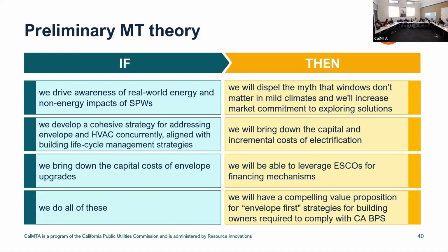And at that point, this needs to be part of our investigation and our research in the next phase, and encouraged by some of what we're seeing with things like the case study from ASHRAE, where they did the energy walk and looked at what would happen. They did the energy walk with, let's just go with HVAC first, and what does this project look like, and then what do we do if we upgrade the building envelope to ASHRAE 2016, and then do HVAC, and learn through that process that it significantly simplified, didn't necessarily significantly change the size of the HVAC, but simplified the implementation of the upgraded HVAC system. And so I think there are mechanisms we don't fully understand, but some opportunities there that we need to better explore and quantify.